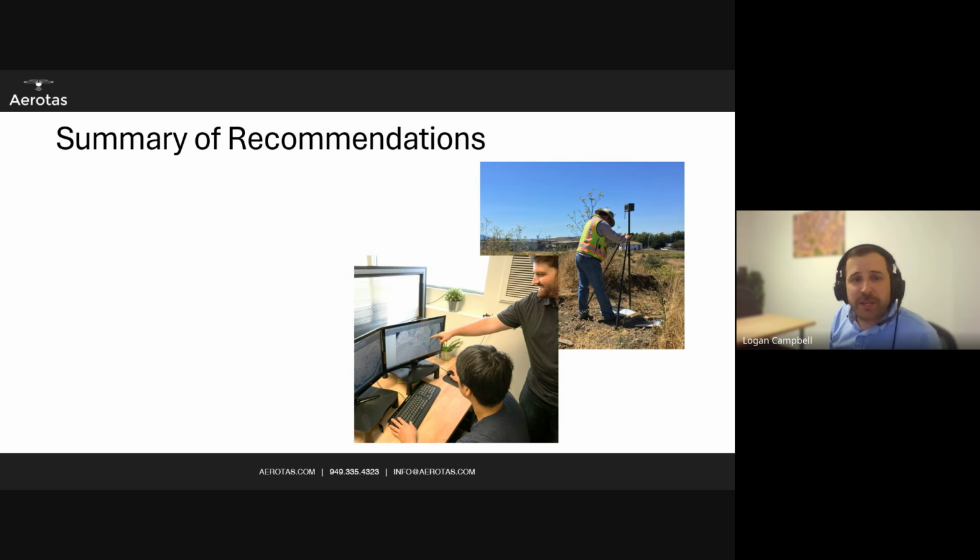Recommendation for flight speed, short answer there, trust your drone's flight computer. Any good drone flight computer, depending on the drone, depending on the lighting conditions, depending on the camera, will adjust its flight, and depending on the altitude, will adjust its flight speed accordingly. You can go very fast on the newer drones at higher altitudes. 30+ miles an hour is perfectly acceptable.